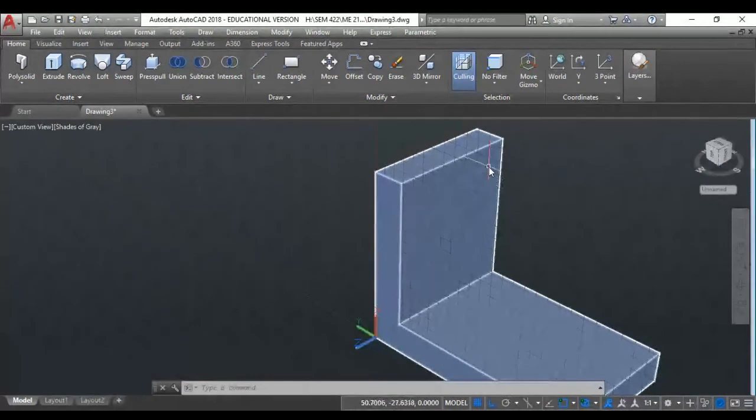For example, the circles are located on that wall. Right? Before I do this, I have to activate this one. What do I mean by activate? It means I have to make that surface my new XY plane. My new XY plane. How can I do this?